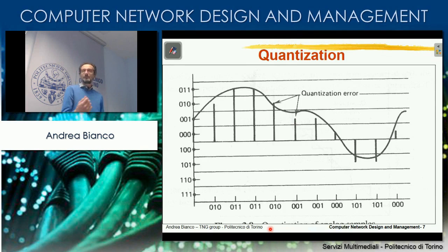Of course, when you start compressing, differential coding, etc., any error becomes immediately more important. The same holds for GSM, which is the CELP coding, in which if you start losing something, since every piece of information is really needed to rebuild in a proper way the original signal, you start having a lot of problems in understanding. Okay, so that's the first thing. First observation, the bit rate required by the application is variable depending on the coding scheme that you use. But the more you compress, the more you reduce the bit rate, the more you are sensitive to errors. These are the most important messages from our perspective that we can extract up to now.